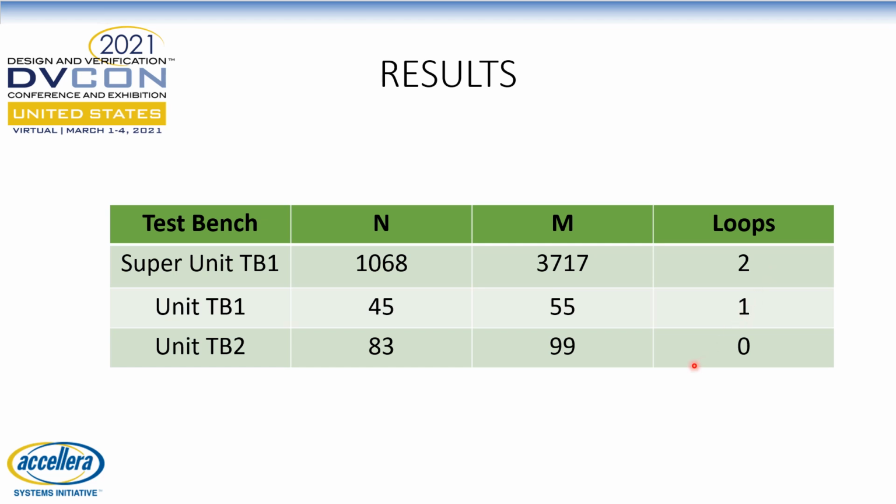We found a very interesting cyclic dependency between the sysmem FIFO in one unit and the CPU response FIFO in another unit, which could have potentially led to a deadlock if one of the FIFOs were not oversized. But we ended up proving that although the cyclic dependency existed, it would not deadlock.